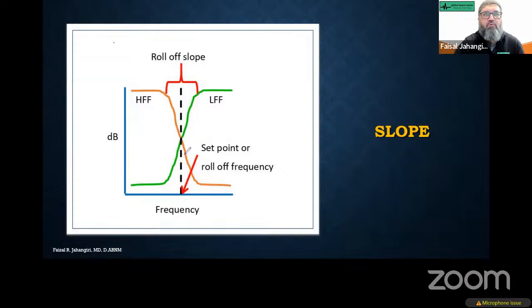So we can do a set point for high cut and low cut depending on whether it's a second order or a higher filter. So there will be some kind of slope. But if you have a -3 decibel slope cutoff frequency, that means there's a 30% drop of the signal at that point with a -3 decibel.